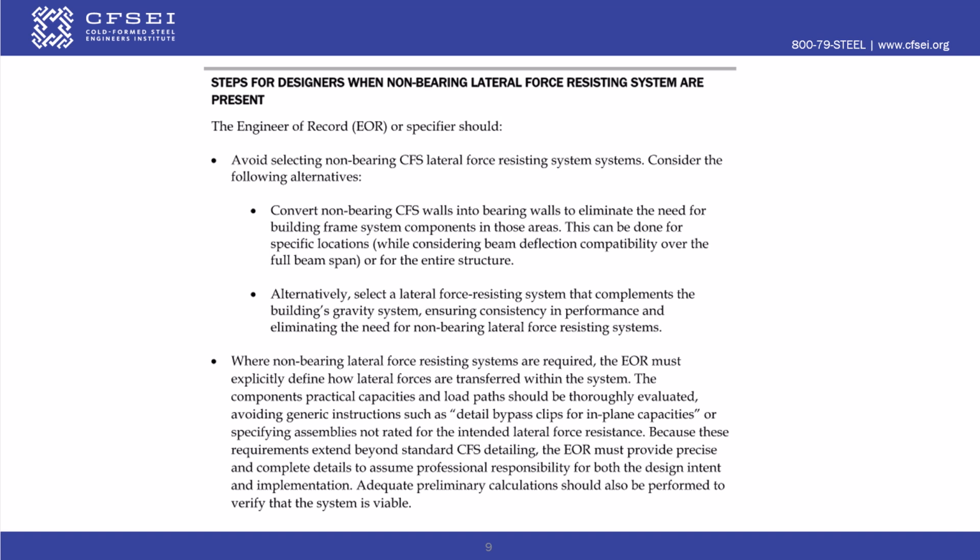If you fall under that niche application mentioned earlier, such as a historic renovation, the engineer of record must explicitly define the lateral force transfer with load-rated components. It is the engineer of record's responsibility to provide this detailing in a thorough manner without vague statements such as "detail bypass clips for in-plane capacities," which is not actually a possible situation. These are complicated, detail-oriented systems that require complete ownership by the engineer of record for general performance integrity.